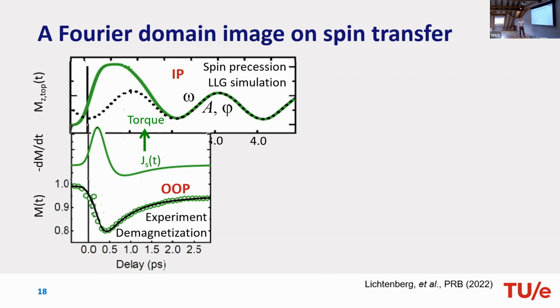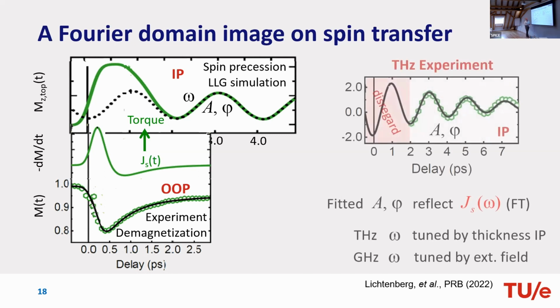Now, we're lazy, so we input it into a mumax simulation where you just have a kind of equivalent torque that you give to the system, and we see what kind of dynamics you induce in a system like that, also in the terahertz range. So this is the result for mumax simulations, or LLG simulations. In the beginning, you have a quick overshoot, and then later on, you can fit the profile that you get out. You can profile the frequency, the amplitude, and the phase of that system, depending on all kinds of input parameters that you have.